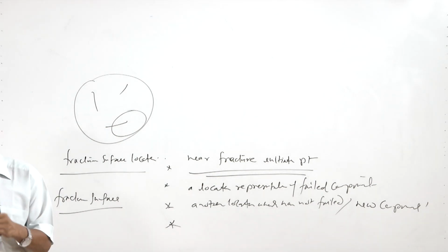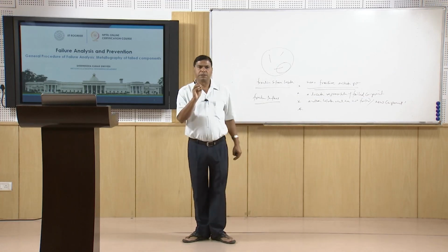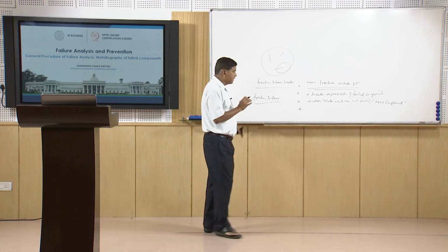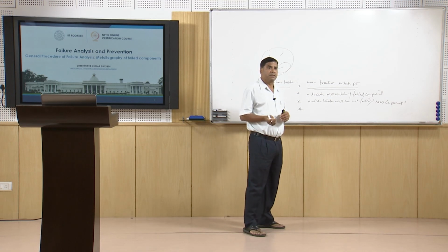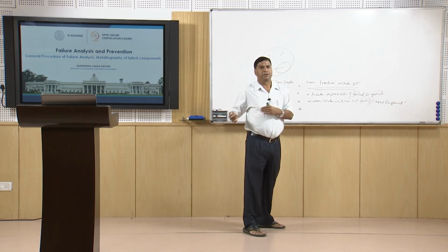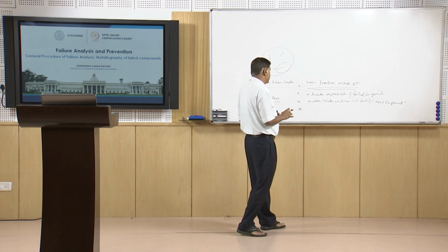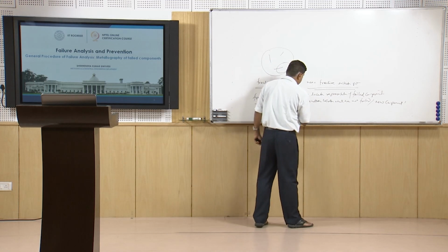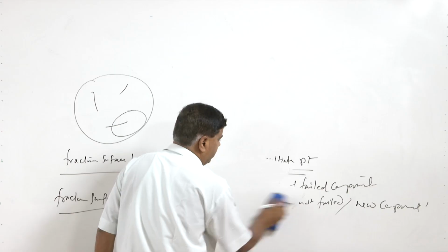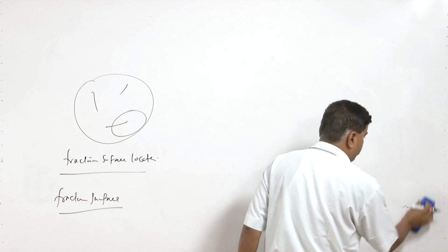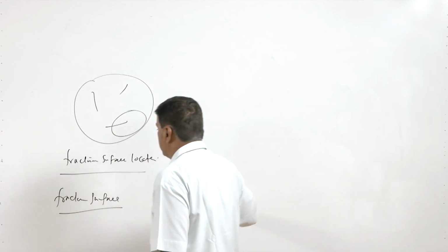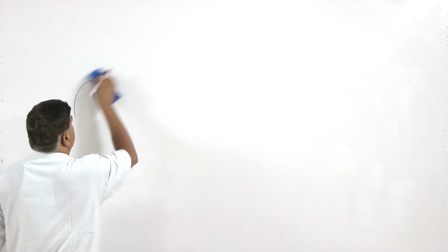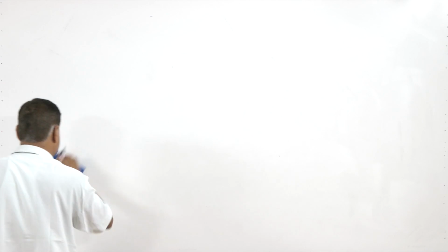Such kind of studies are of specific and more importance, especially in the fatigue fracture, especially in the region where the crack has nucleated, to identify if there was some kind of defect, or some kind of decarburization has taken place, or some kind of inclusions or pores were present, which have led to the nucleation of the crack to cause the fracture of the component. So, the fracture initiation point definitely becomes of importance in the failure analysis.